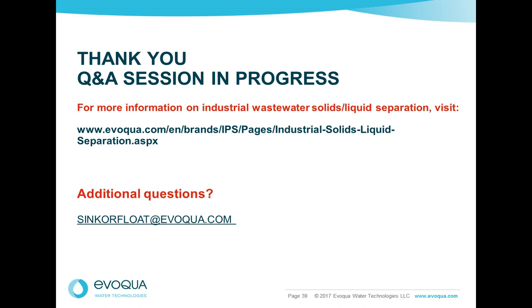Yes, in the Biomag as well as the COMAG process, the magnetite is recovered. It's recovered in a magnetic drum separation process, in the case of Biomag, from the biological sludge. It's recovered from that as part of the wasting process, so that you waste the biological sludge. You do not waste significant portions of the magnetite. In the case of the COMAG, it's separated from the inorganic solids and kept within the system. Typical recovery rates are anywhere from 95 to 99%.